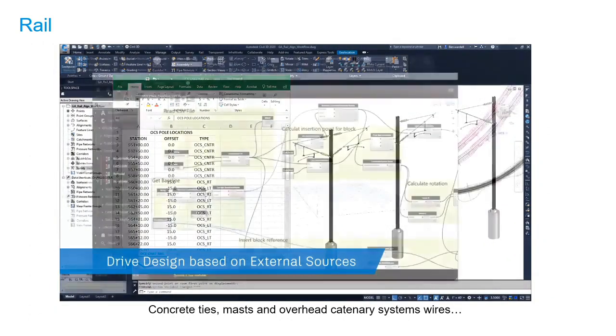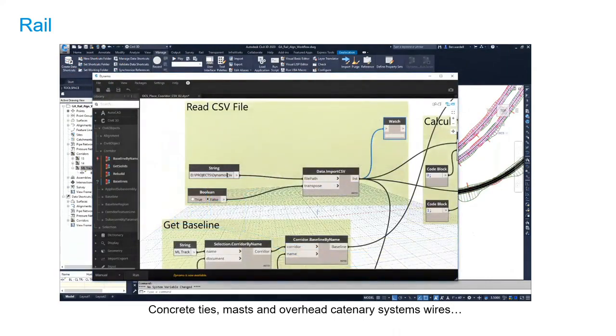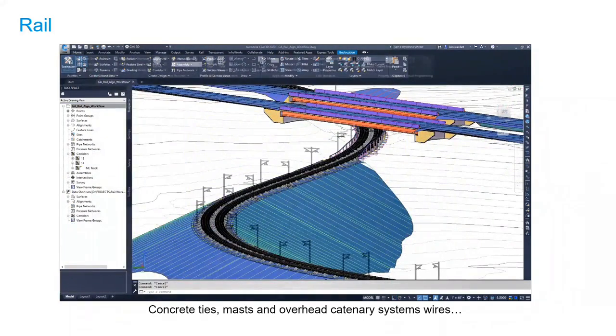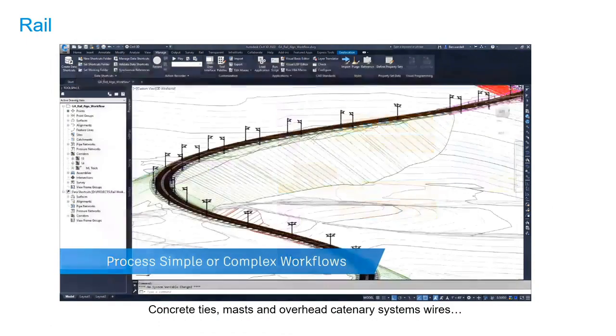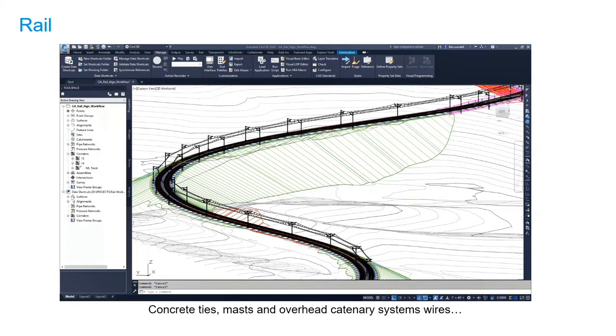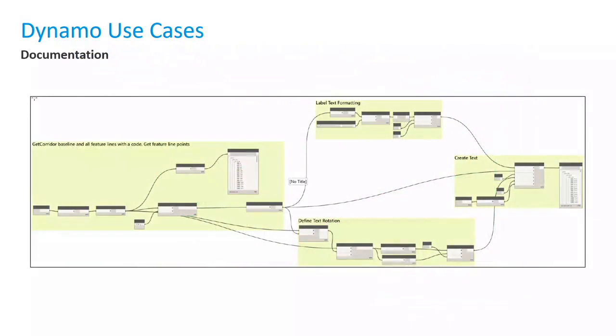Here is the CSV file, just an example. You have the item. You have an ID. And based on that ID, I can link it to a certain block in AutoCAD and place that 3D block within my 3D model. So it can vary. It doesn't have to be one single element. It's reading all of the AutoCAD blocks. You end up having a 3D model in no time.